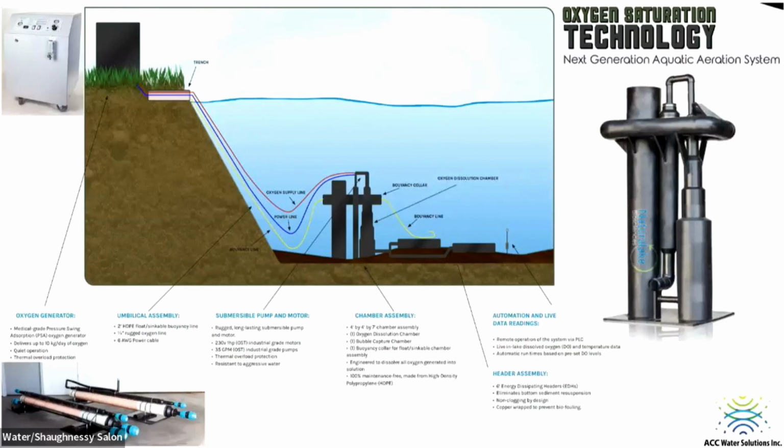So it's changed things. It's side stream aeration, but it's not side stream aeration. It allows us to maintain the temperatures because we're not pumping the water for long distances. We see no temperature change. The water itself keeps the system cool. It is probably the biggest jump we've had in oxygenation technology. Nothing new in it. Just the way that it was applied allows us to use it in small water bodies. As long as you've got about 8 to 12 feet of depth, you can usually find a way to make this work. Downside, pretty big capital cost. Upside, easy to use, easy to put in, and very, very low operational costs. There's very little maintenance and cost associated with it.